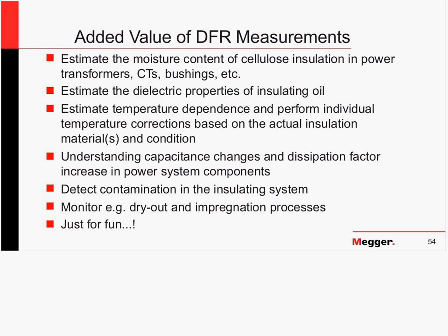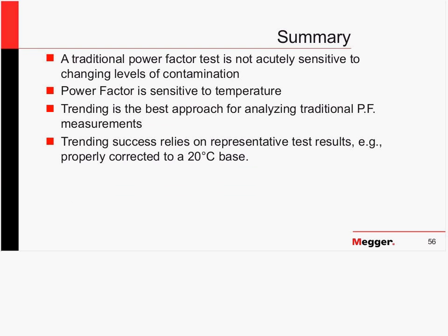So just to wrap this all up and summarize, a traditional power factor test, I'd say, is not acutely sensitive to changing levels of contamination. It is sensitive to temperature. If you're going to still continue to rely on just a single point power factor result, I would tell you trending is your best approach for analyzing it, but your success is going to rely on you having representative test results.